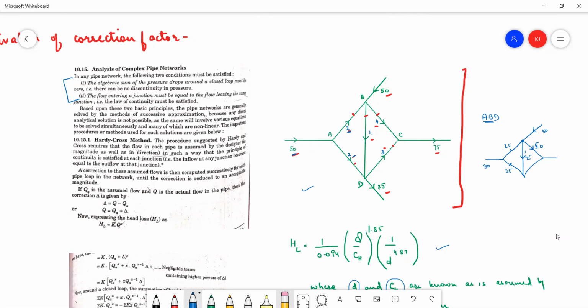And also at this particular junction, we are given that outflow is 25 units. So incoming is 50, outflow is 25, so here it goes 25, and finally here it is given 75, and we can see it balances, that 50 is coming from here, 25 is coming from here, and it is balancing here, right? So the flow distribution is done. I'll quickly show it.